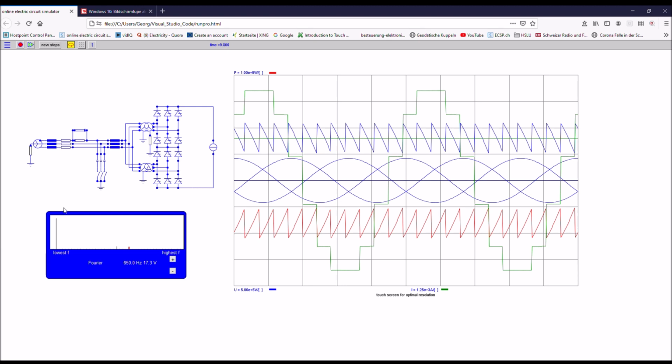So you see that typically when you measure the current, this is what you can see in green. This current has harmonics, this is the harmonics measurement. And you see the 50 Hertz, the base frequency. But then you see the two spikes here. This is the 11th and 13th harmonics, which represent 550 and 650 Hertz for a 50 Hertz signal.